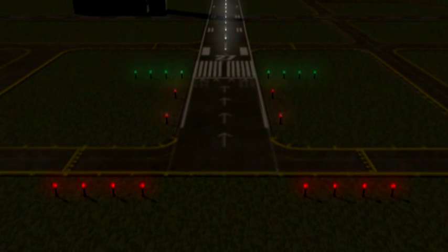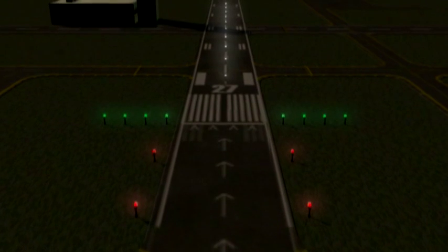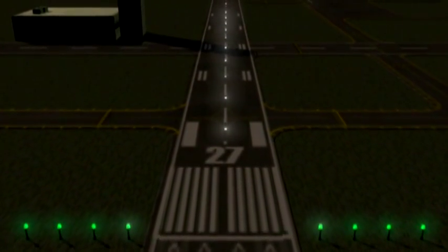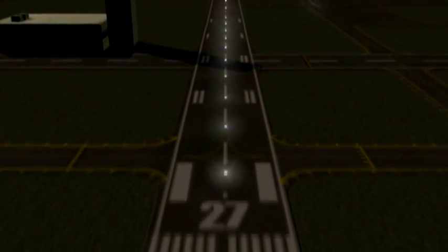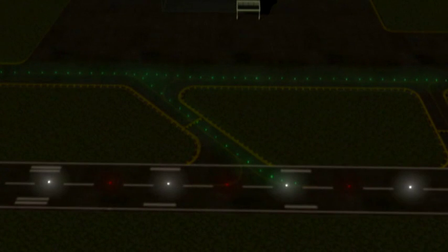In-pavement lights, which are installed on some instrument runways, are also color-coded. For example, touchdown zone lights are white. Looking from the landing threshold, the runway centerline lights are also white until the last 3,000 feet of the runway. Then, the white lights begin to alternate with red for the next 2,000 feet. And finally, the last 1,000 feet of centerline lights are red. In the past, taxiway centerline lights were all green, but under a new international standard, the green lights will alternate with yellow ones on the runway side of the taxiway hold line.